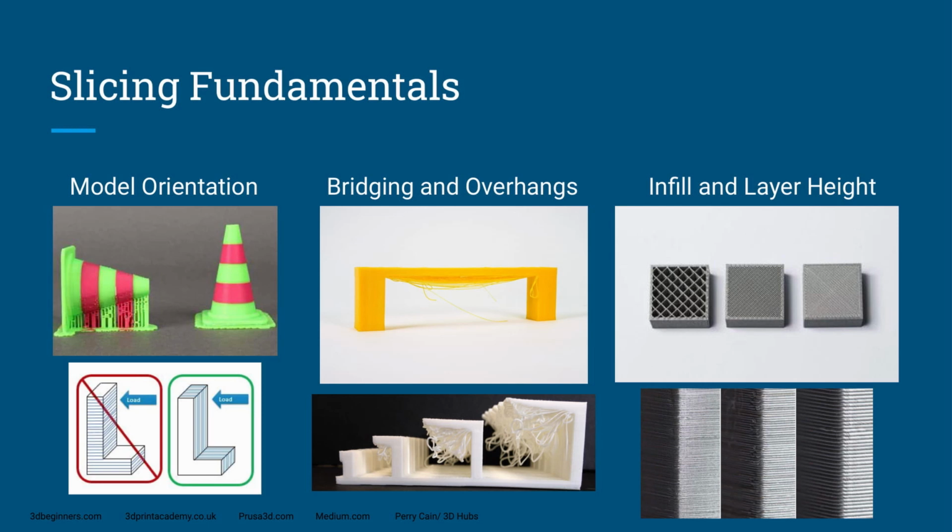So there are certain advantages and disadvantages of different layer heights. Like the thinner the layer height is, the more detail you would get, but also it's going to take a lot longer to print. Also, if the layer is thick, it'll print a lot faster because it's actually laying on bigger layers at a time, but also you're not going to have that same print quality. So you can print slower with higher detail or print faster with lower detail. So you have to pick and choose what height you want your layers to be.